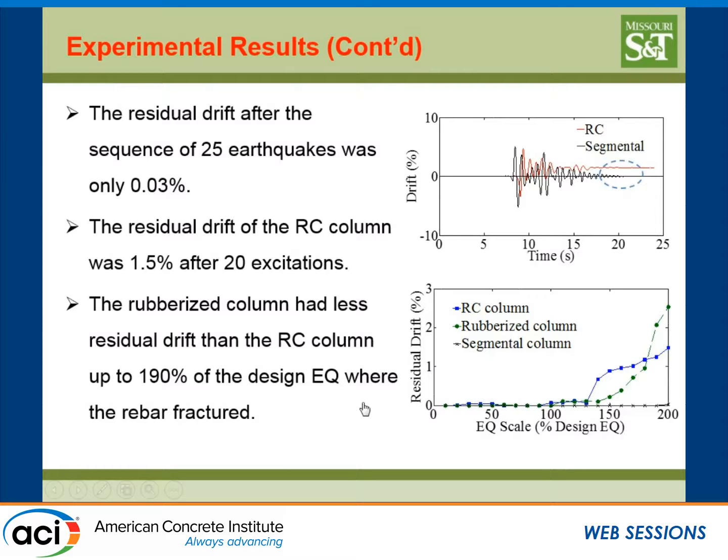And now for the rubberized concrete versus the regular one, here is also the residual displacement. They behave very much the same, and here we start to see some yielding and more rupture on the reinforced concrete. So this is why you see a higher residual displacement in the reinforced concrete. The rubberized one is still working much better, and then all of a sudden at 190 you rupture your bar in the rubberized concrete, and this is why we see a huge increase in the displacement.